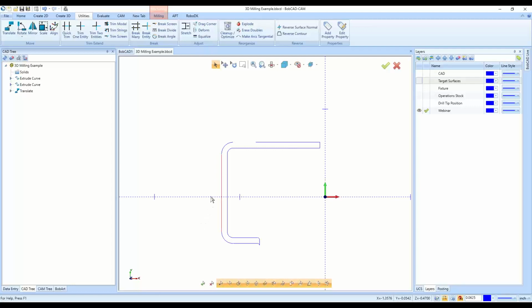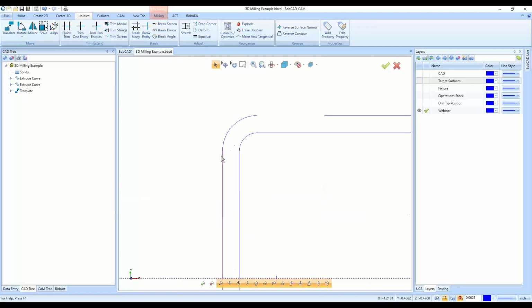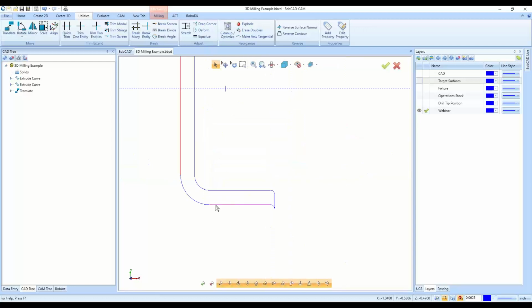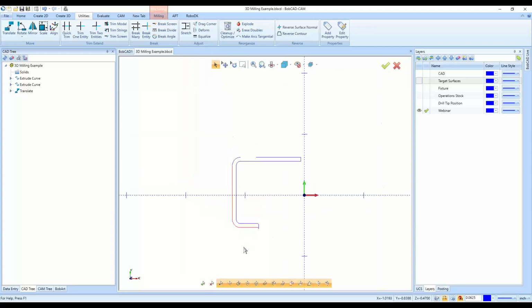That way the software knows that's my start position of the chain selection. And when I hold Shift and click, I want to just select this line, this arc, and this line. I want to hold Shift and click in this area of the line, this halfway mark, to chain select it correctly of what I want it to do.